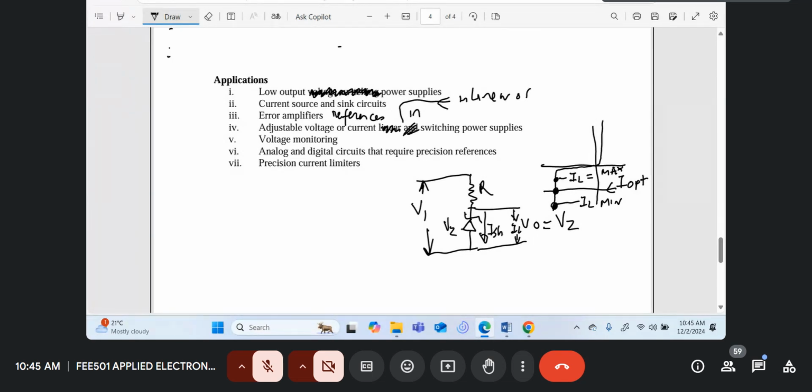It can also be used. Now, how do you monitor voltage? If you've got a circuit, say with voltage V0, you want to drop a very large voltage. Like if your DC voltages are high, like in some switching power supplies, where they get the voltage directly from the mains. When you rectify it, you get say 350 volts. But you want to monitor a section of that.